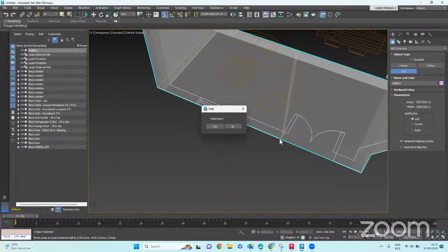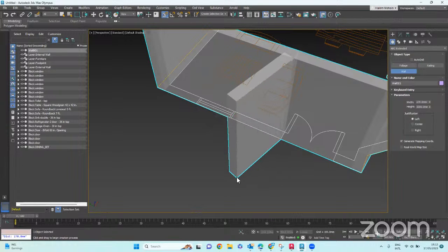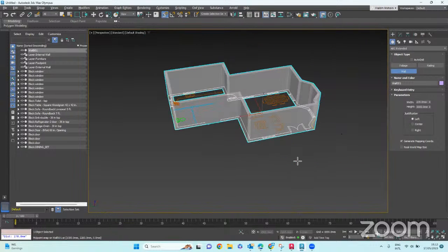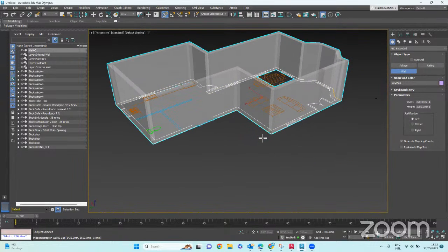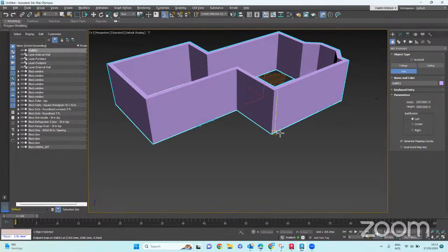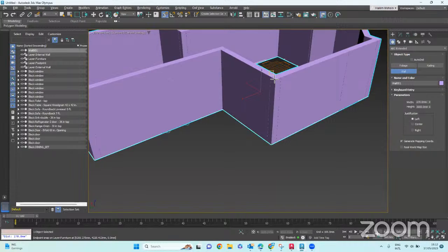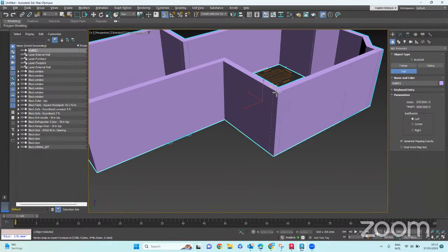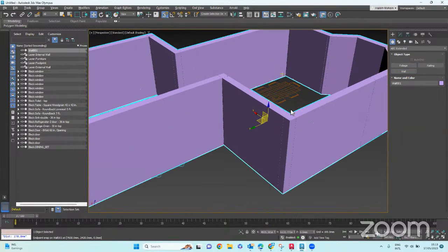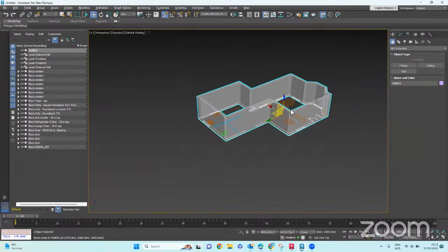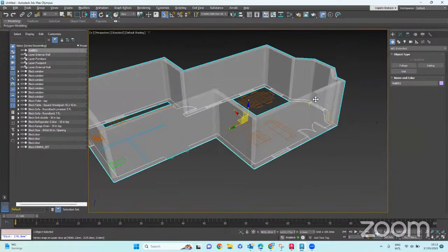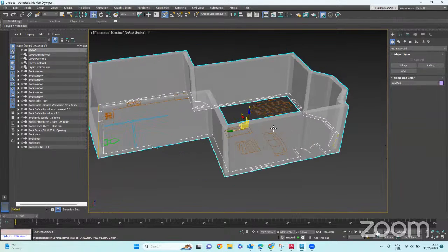Click here. So when you made the starting point, it will ask us, do you want a weld point? So you can just click yes, and then you can click escape. Basically, you are done with the wall, and you can press alt X to see the walls in the default mode. But you can always go back and click, make sure the walls are selected, and press alt X. So you can toggle between these two visuals.